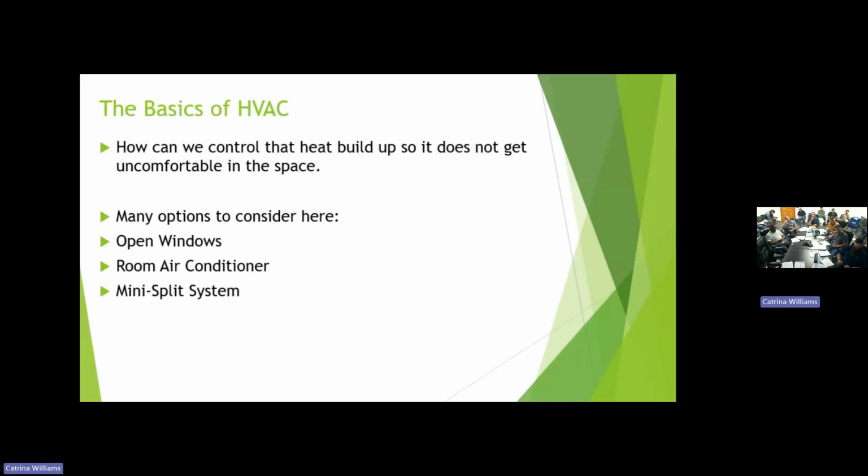But now they've got the mini split system. Really, it's like a room air conditioner, but this is split in two pieces now. You don't have to have that big opening in the wall. You've got the fan and the cooling coil on the inside, and all you do is run the lines through the walls to a lot smaller openings. Then you've got an outside section, like a regular residential heater or cooling unit. So that's a mini split. It's a ducted system only for the one space. It only does that one space, but it can handle that area.